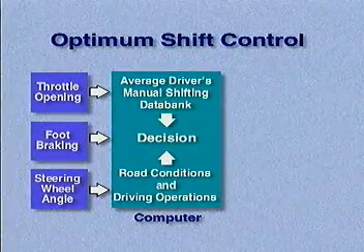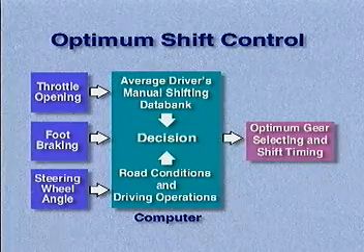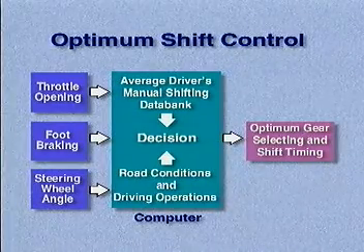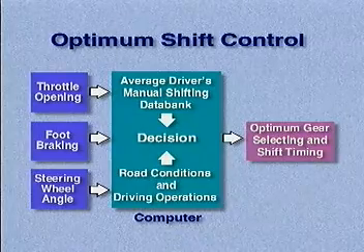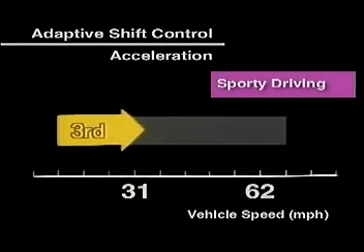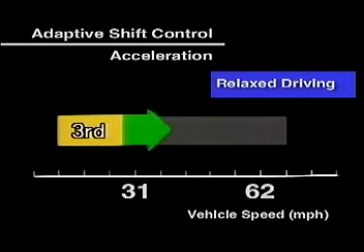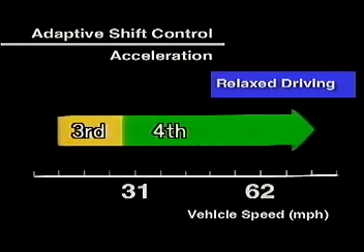With INVEX 2, feedback and learning capabilities are added to fuzzy logic to modify the transaxle shift pattern according to driver preference. As the INVEX 2 system learns a particular driving pattern, it modifies its shift control pattern to favor an aggressive sporting driving style or a relaxed mellow driving style. In order for the transaxle to operate correctly, the TCM and all of its electronic components must be functioning properly.